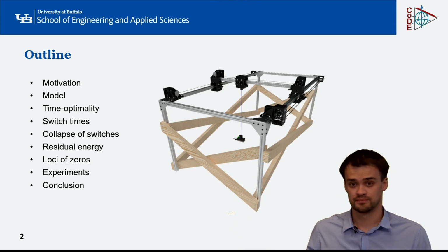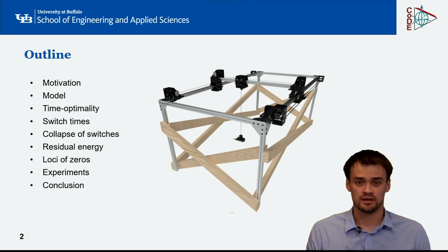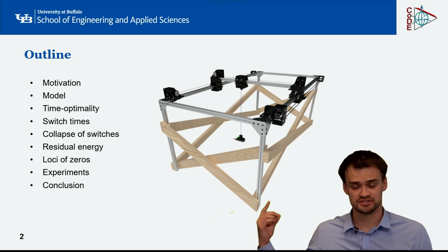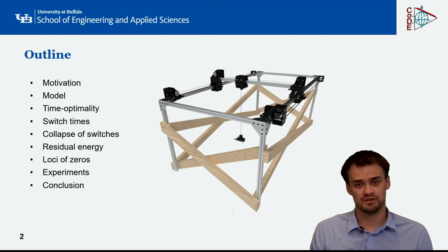This is a gantry crane. Assuming that the velocity of the gantry crane can be controlled, a bang-off-bang control profile is derived to bring the payload from a position of rest to the terminal state with no residual vibrations.